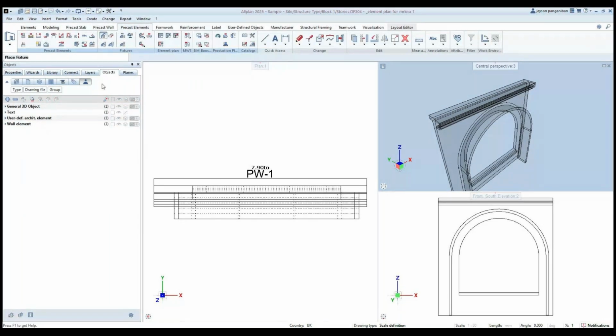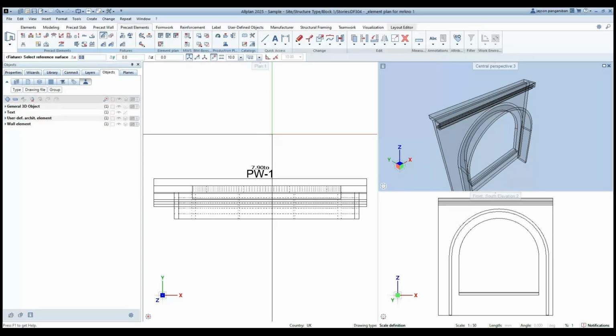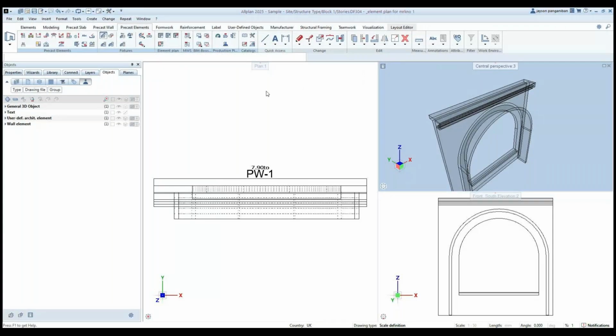So first from the catalog, I have these lifting anchors. Okay, so I can make use of any of these lifting anchors, and I have created this in the model in the orientation like this. So what I wanted to see on this element is that it should be on the surface. So this part will be on the surface. Okay, so what you're going to do is just select this, and as I have highlighted on the presentation, I need to define the orientation to make this in the x-axis, so this is very important. And then I need to rotate this 180 degrees because on a surface you have to rotate your view.